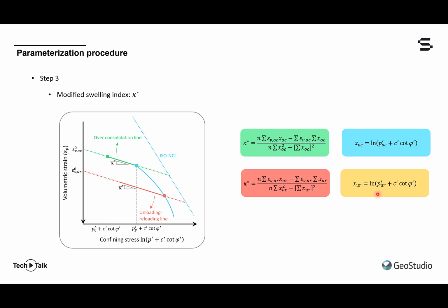So I just want to point out here that the reason this blue line exists right here is you can imagine a scenario in which the specimen is prepared in the triaxial chamber. It is isotropically compressed to, say, this point right here, where it is then sheared in triaxial compression. And if it yields immediately, then it would track along this line, and it's at this point where unloading might occur along the kappa line.